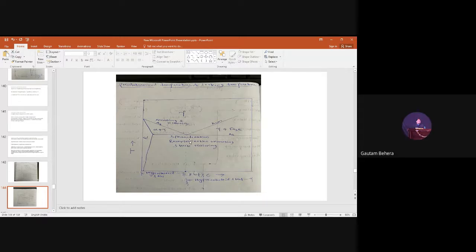Sir, explain it on the basis of temperature. The phase is changing above T1. T1, nothing is T1 here. That eutectoid point temperature, is that T1 or A1? A1, sir. Yes, above A1. Only A1 or any other thing? A1, A3, and ACM.